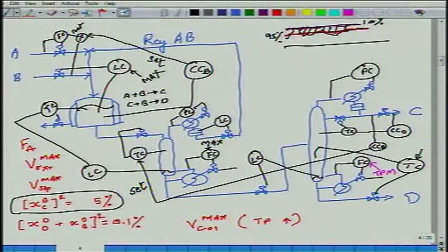If boil up has increased, level will start to go down because you are boiling off more stuff. So I will start sucking in more from the stripper. Level of the stripper will go down. Level is going down, so the stripper level controller is saying jack up production, increase the temperature. Temperature increases.